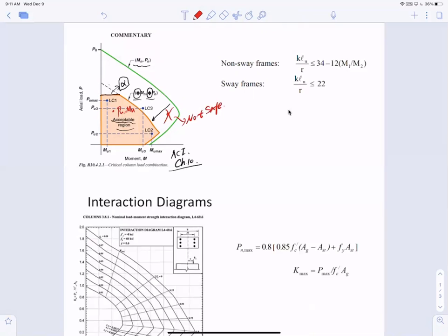So we've been talking about this column forever, right? It seems like you already have a good understanding of the interaction diagram, but there's a critical issue here: this design was done under a short column assumption. That means there's not much buckling, no buckling, and small lateral deformation. How do we ensure that?